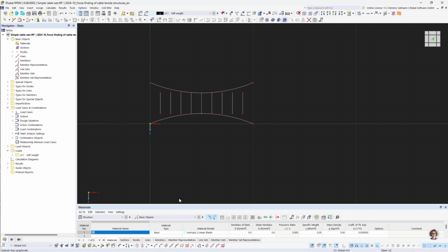So if I click on it and hover over the end of a line, it automatically searches for other lines in that plane and creates a preview where an intersection has been found. And if you click on it, the intersection has been made and the line is extended to the other line. And that way, complex intersections can be made quite easily and fast.